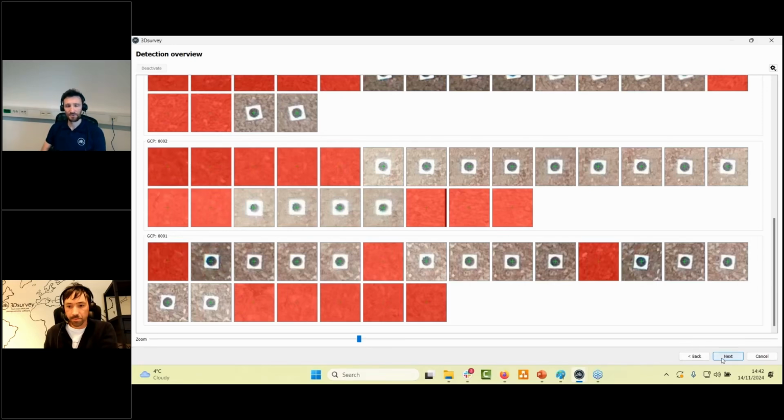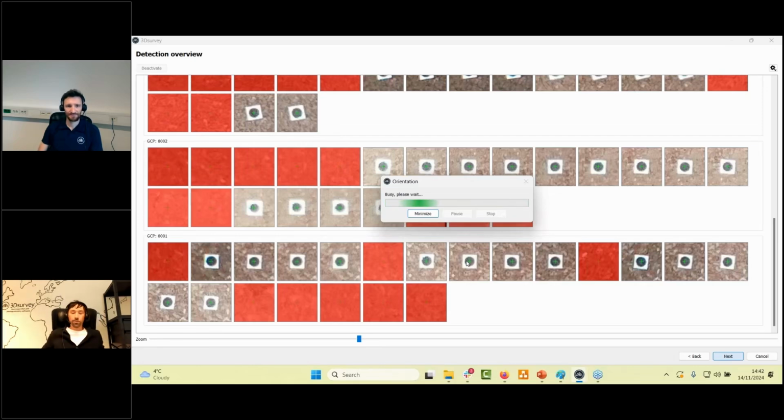You can actually use this also in batch processing. That's my point. So if you have our 3D survey targets, or if you have a checkerboard or AprilTag, you can do this in a fully automatic way also in batch processing. Great. What's different here? If you go step by step, you just have more control. So you can decide and go one step back, improve this, or correct the positions in this step and get results maybe a bit better in comparison with the batch approach.